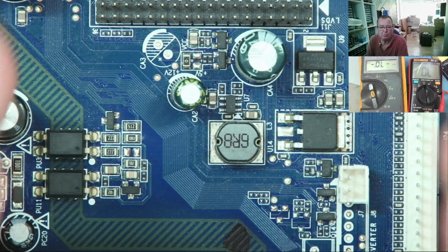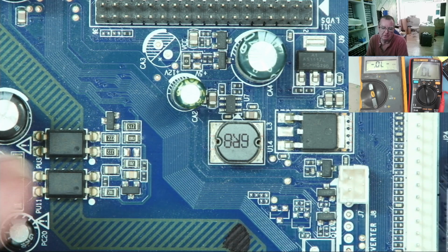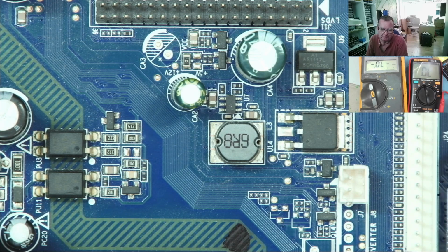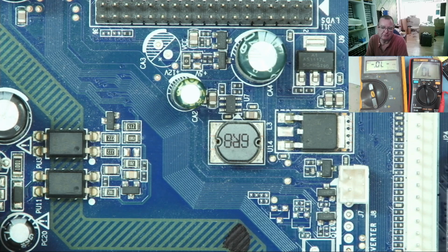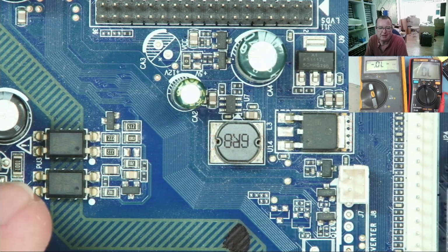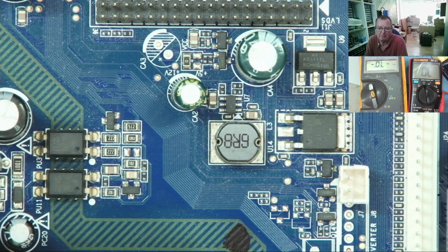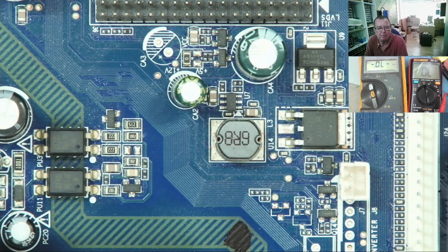Now, I won't say this will work all the time. If there is a low enough value resistor from the base to the emitter, or from the gate to the source on a MOSFET, you may not get enough voltage to turn the transistor on. But you can always check for that. You can think, okay, it's not turning on. Measure base to emitter in resistance mode, or measure to ground from base or gate in resistance mode, and you'll soon know if you have a low value resistor there.